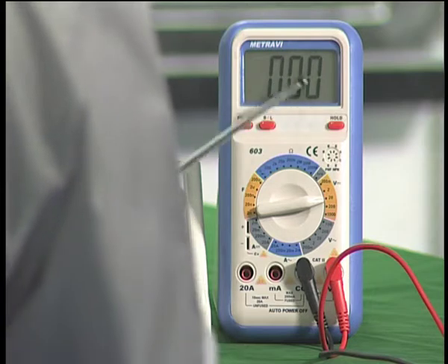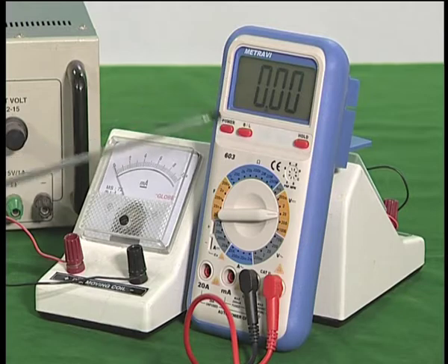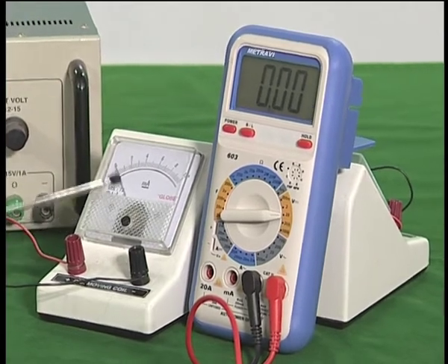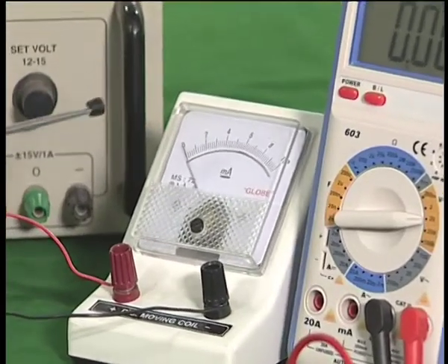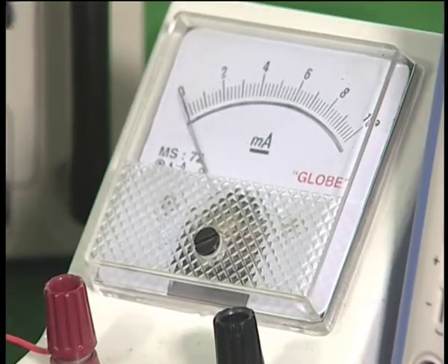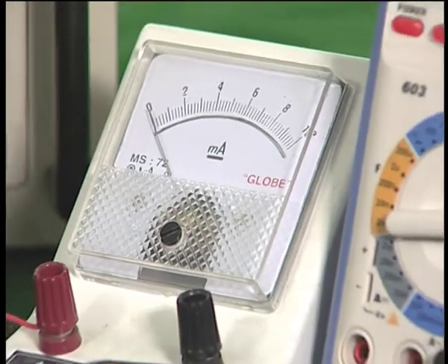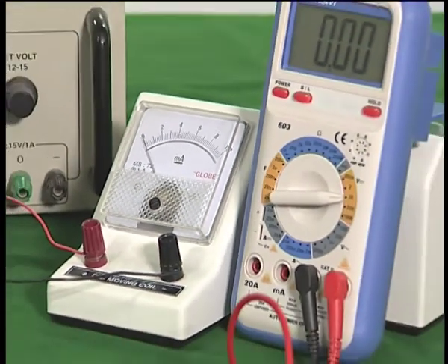This blue voltmeter is going to measure the VDD voltage, VDS to be precise, and this current meter is the one which is going to measure the IDS, the drain source current, for different gate source voltages. No other current meter is required because we are only going to vary the gate voltage and measure.